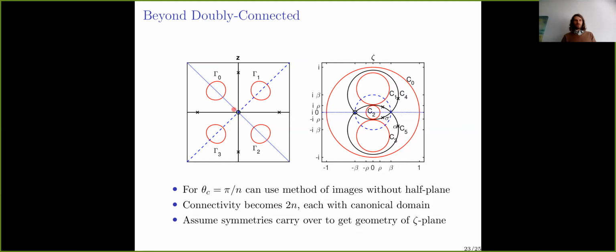So here it's pi/2, and we can imagine here's our physical vortex. We put image vortices over here to satisfy the condition that it's the streamline. And all that symmetry I talked about is the same idea, but it becomes a little bit more complicated. We're considering symmetry about all of these lines, essentially. I'd like this boundary to go to this boundary when it's reflected about the blue line y = -x. Same story for y = x. I also want to insist on symmetry basically about every reflection of a line.